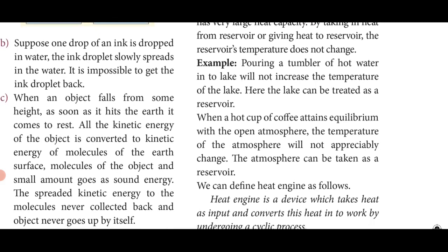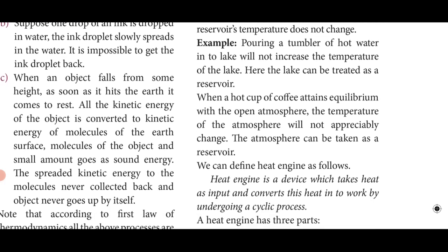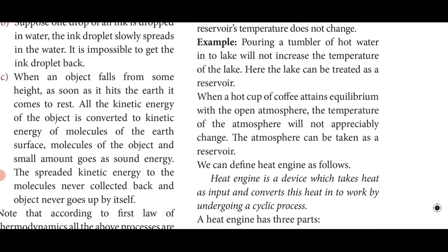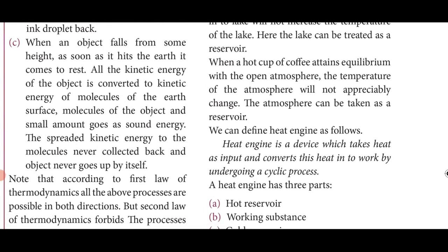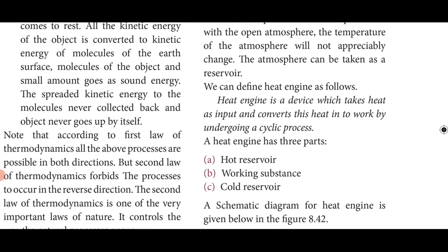For example, if you pour a tumbler of hot water into the lake, it will not increase the temperature of the lake. Here the lake can be treated as a reservoir. Like that, when a hot cup of coffee attains equilibrium with the open atmosphere, the temperature of the atmosphere will not appreciably change. The atmosphere can be taken as a reservoir. That means if you give a small change in heat, that would not change anything significant in the reservoir.